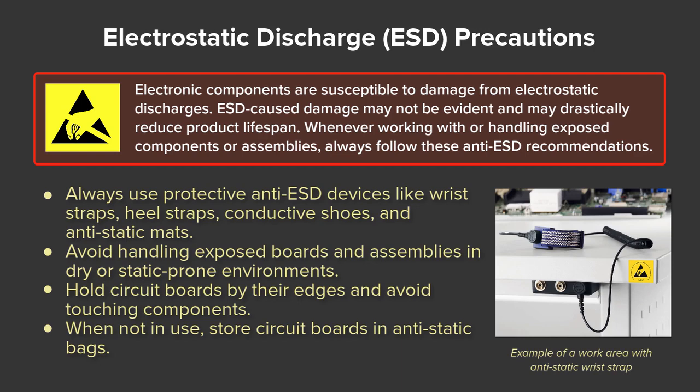Always use protective anti-ESD devices like wrist straps, heel straps, conductive shoes, and anti-static mats. Avoid handling exposed boards and assemblies in dry or static-prone environments. Hold circuit boards by their edges and avoid touching components. When not in use, store circuit boards in anti-static bags.